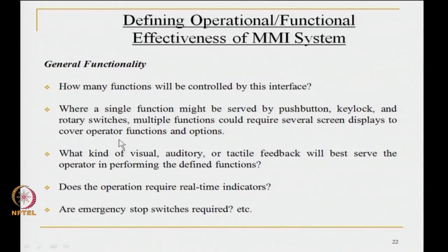Where a single function might be served by a push button, key lock and rotary switches, multiple functions could require screen displays to cover operator functions and options, and at each stage you check whether the user wants to continue. The next question: what kind of visual, auditory or tactile feedback will serve the operator in performing the defined functions? Does the operation require real time indicators? And finally, an emergency stop or switch may be installed.